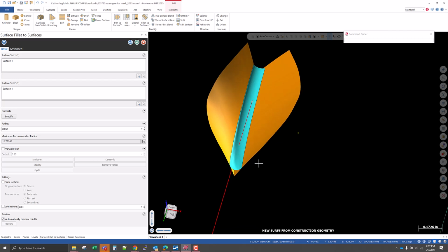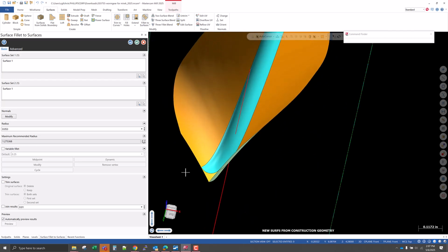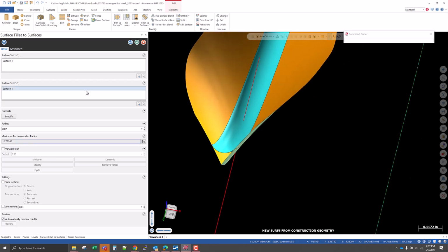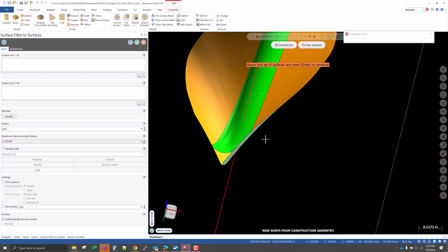And so if I was going to rough that out, for example, with a 125 end mill, that radius, 063 or 0625 for the actual size tool, well, I might give it a 0.07 radius. So I'll generate that first, 0.07, and apply.